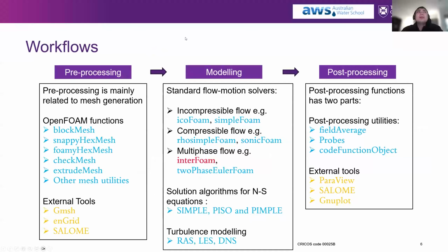Just to give you a brief on the workflow. The way OpenFOAM runs is the same as the way other numerical solvers for 1D, 2D hydraulic modeling run as well. You have the pre-processing, you have the modeling, you have the post-processing. For the pre-processing, it's mainly the mesh generation section.